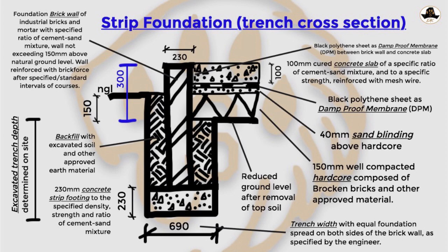We use industrial bricks for this one because industrial bricks are stronger, they're fire resistant, and they do not absorb water easily. So we can trust their strength in the foundation, and the foundation will last long. In some countries, the standard lifespan of a house should be around 60 to 100 years. So you need a very strong foundation, and industrial bricks have proven to be very good at that.